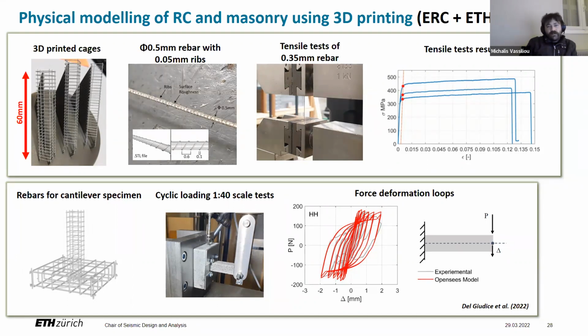Okay, and for standard rebars, you would expect this dispersion to be smaller. But I think this has to do with the size of the steel powder that we were using. We need to use a smaller one because this essentially reflects imperfections over here, which we need to reduce. So these were some tensile tests.